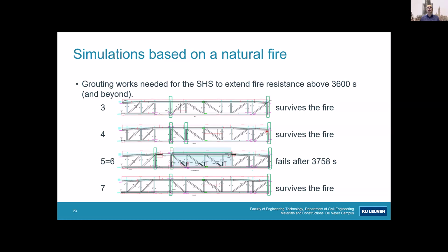Then we did the same thing for truss beam 4. So here we had the advantage. This diagonal was working in compression, but it was 25 millimeters in thickness, and this was only 20 millimeters. So this was more stiff and reacting more stiff than this one. Therefore, there was some distribution of moments, and therefore also here the second stud must be grouted.